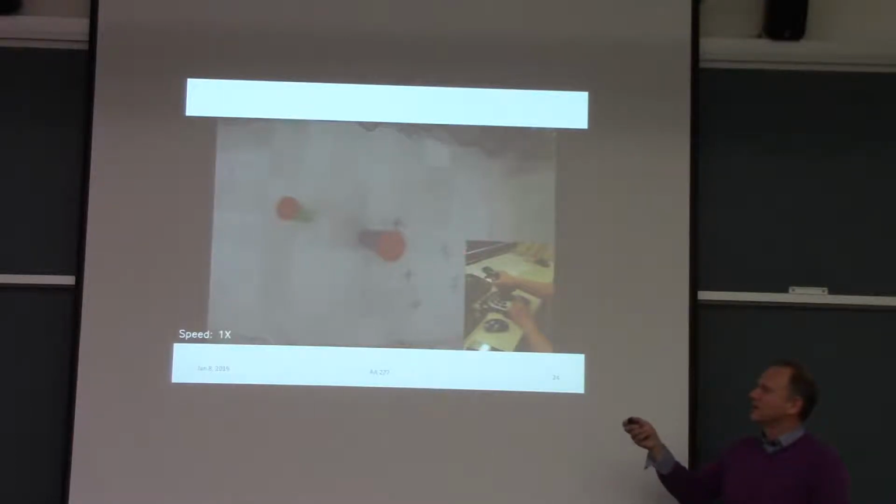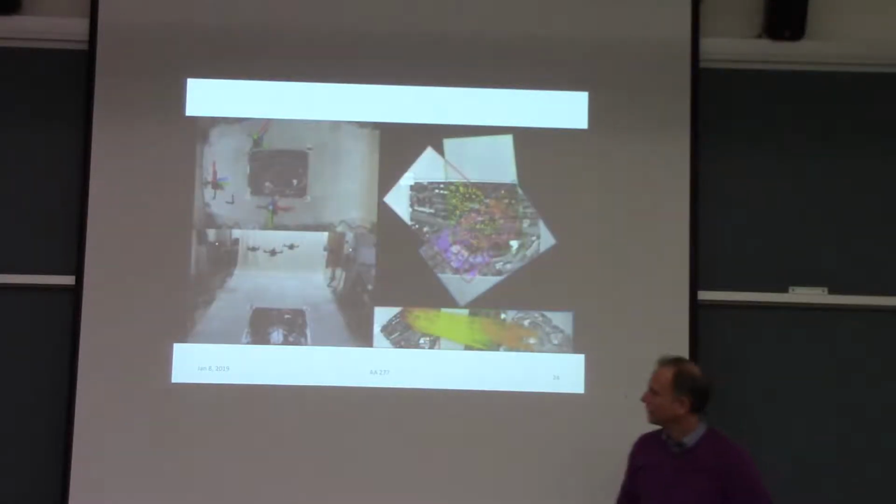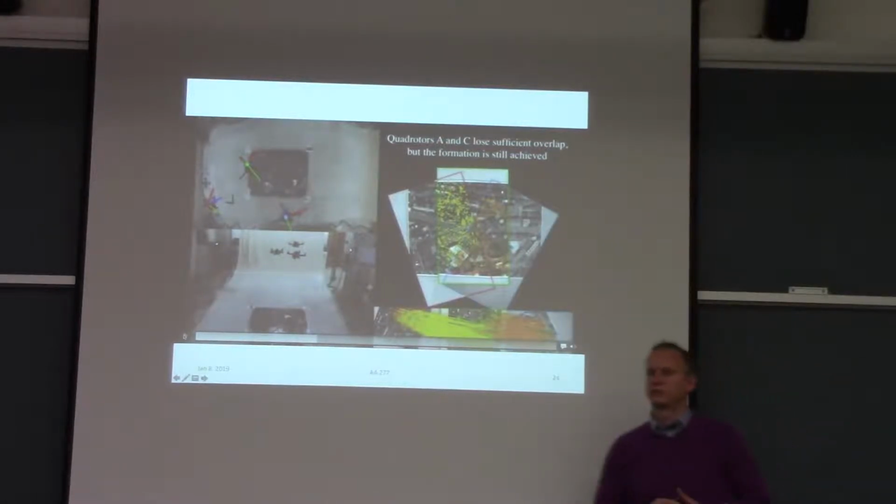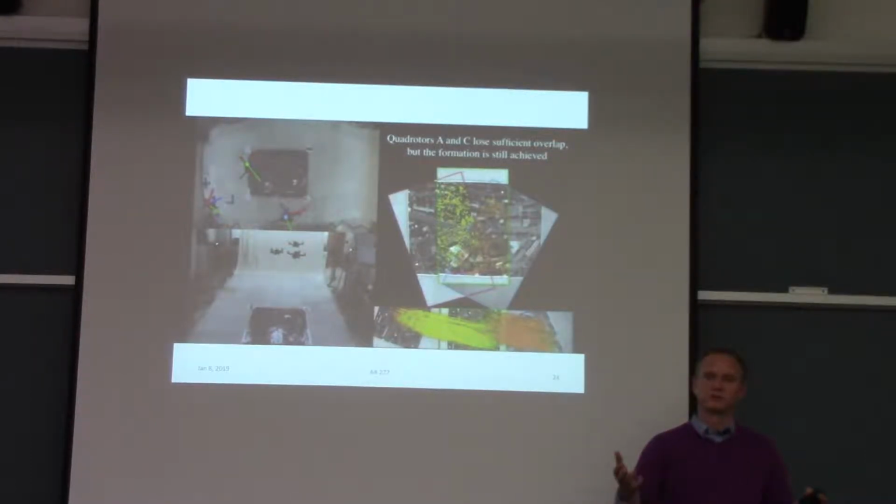This is a variant of that algorithm where my student Ding Zheng has been able to, let me pause this, been able to fuse formation control with human-robot interactions. So basically you have an efficient way for a single human to command a large swarm of robots, and the human controls that swarm of robots as if it's just one individual sort of super robot, and then the robots take care of themselves to avoid collisions and to kind of hold their formation as well as possible.